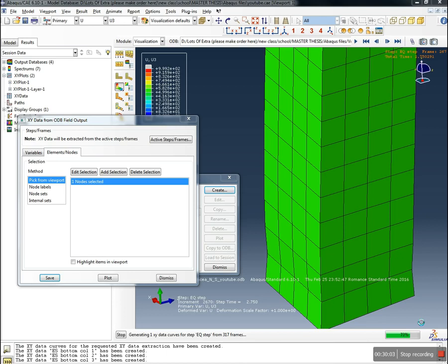But what I wanted to say is that the stirrups normally for the bottom column are much closer to each other. But this of course comes from some design consideration. You have to check what stresses you have there, and design the stirrups. Again, we are not using design here, so I just know based on experience as well that